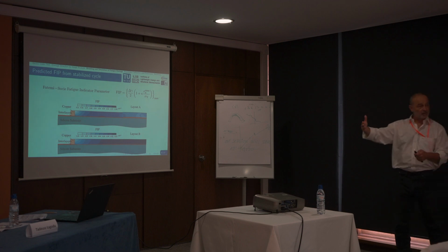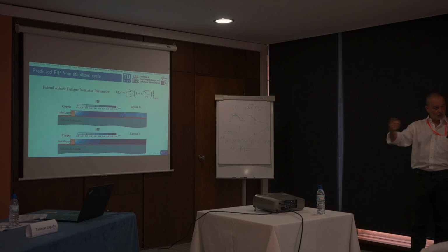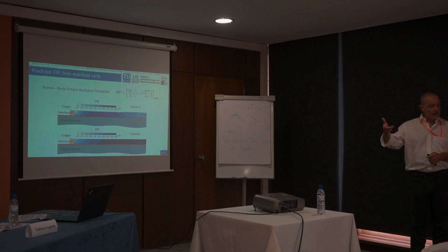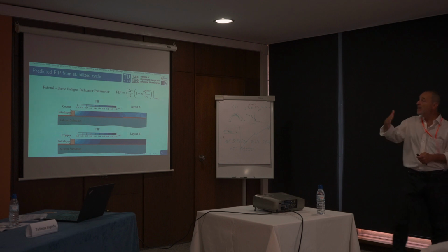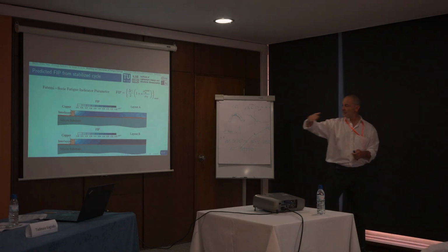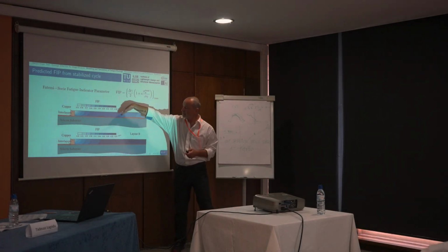So since we have plane strain, we also have mechanical strains. Total strain is plane, but the mechanical strain is also out of plane. And the implementation we have is for full three triaxial strain states. And it may happen that the critical plane is also inclined.